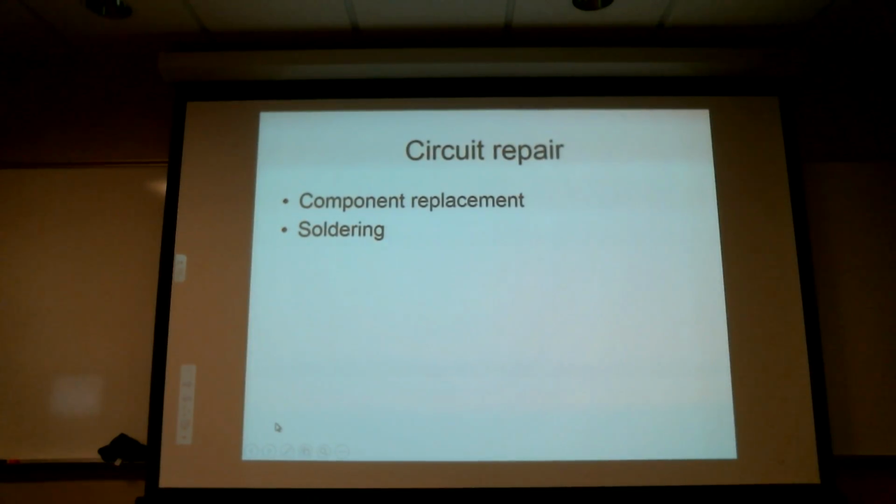Okay, what's the difference between an ammeter and a load meter? And what does that mean for you? Ammeter measures current into and out of the battery. Load meter measures current coming from the generator. It hopefully isn't going back to the generator. That would be bad.